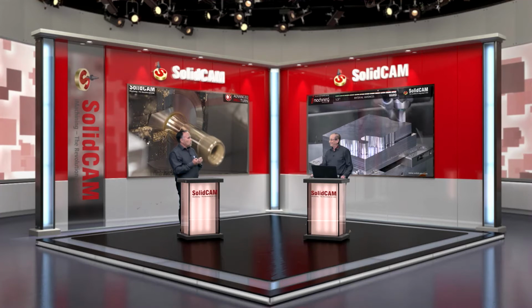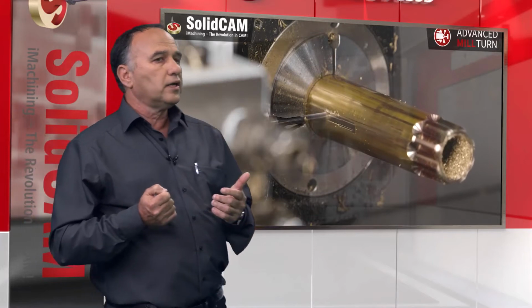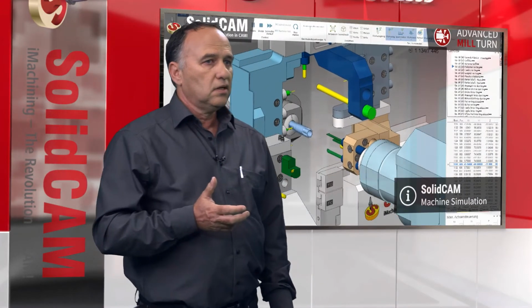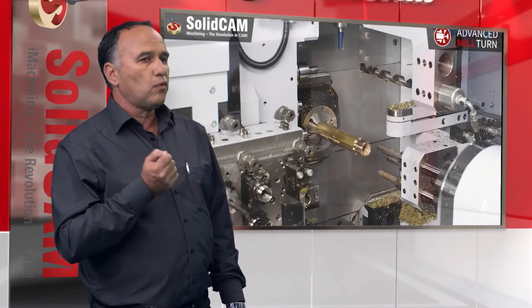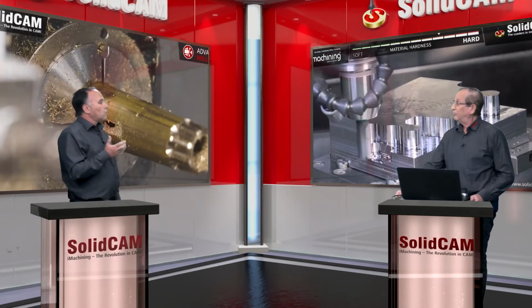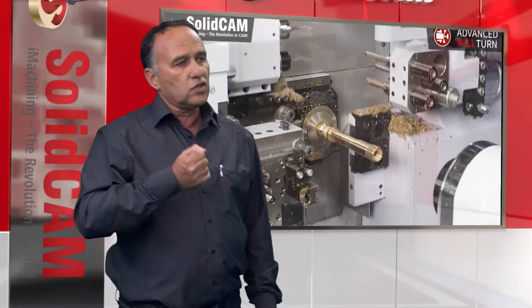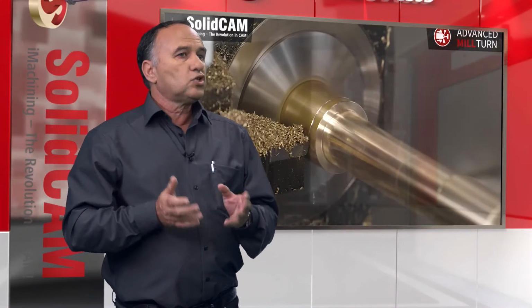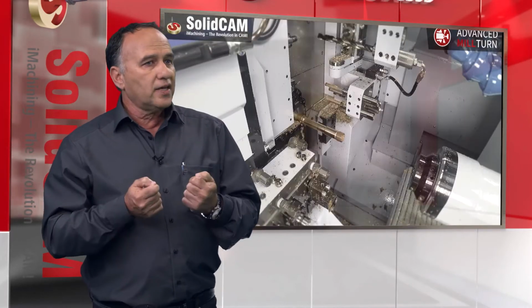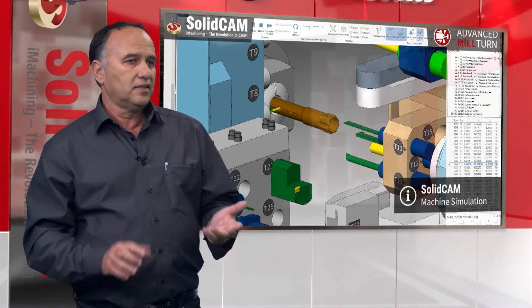So the operator wishes to make minor changes, like, for example, increase or decrease the step down for the pocket, to make some changes in the cutting conditions. So now with the shop floor editor, the setup operator can make these changes easily. And the last thing is outsourcing programming, we call it. Yes. Some companies are using outsource companies for their machining or a subcontractor. So instead of receiving just the G-code file and sending it to the machine, the machine operator can receive the CAM part, check it, make minor changes if he needs, and simulate the process before machining, thus understanding it better and making edits as needed.